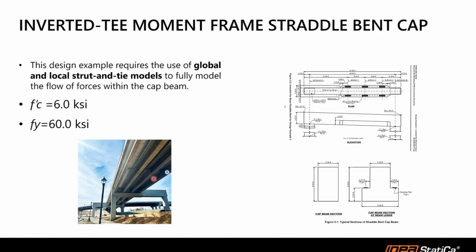And if you look at this picture, you will also see a similar structure where there is a rectangular cross-section and then it changes because we need to carry these girders here, and then you'll have some reactions on this ledge, right? Because the section changes and you want to see the stress flow on those ledges, we need to create a local model of that cross-section. So in the example, they do that strut and tie model for that cross-section. And then in the Detail application, we're going to do a similar approach.